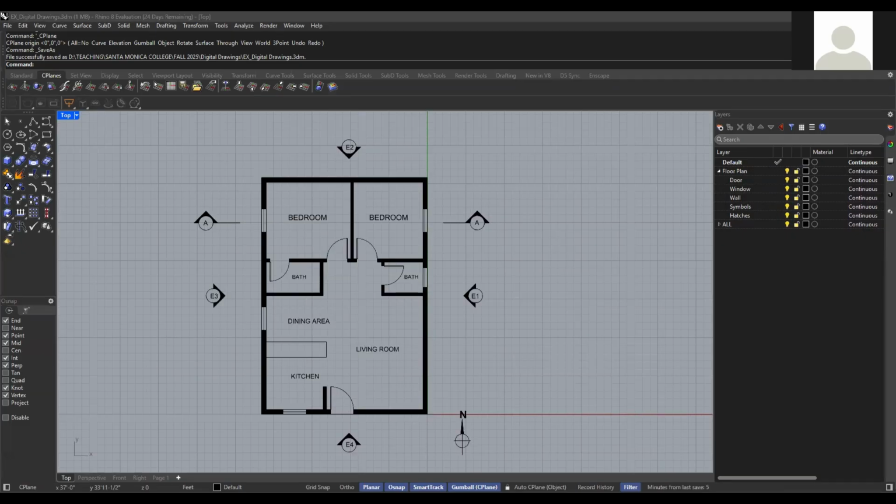And you can use consistent layer names and colors. This helps when adjusting the line weights later, so you can work smoothly. Also, make sure all drawings are aligned to a scale and drawn in the top view.